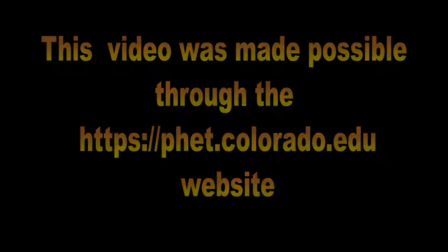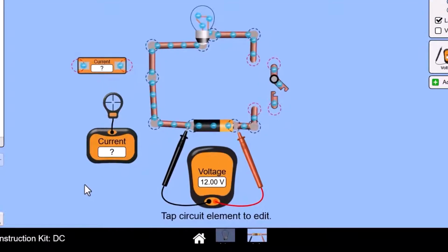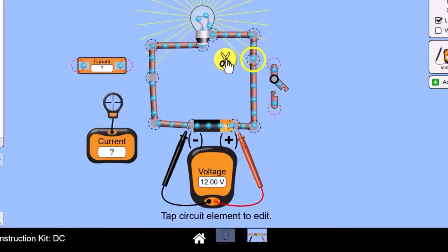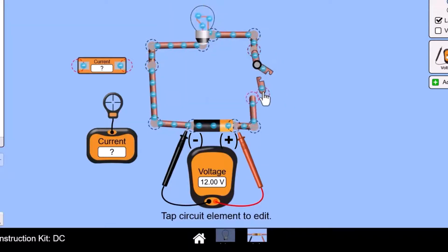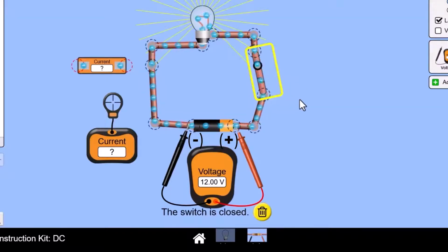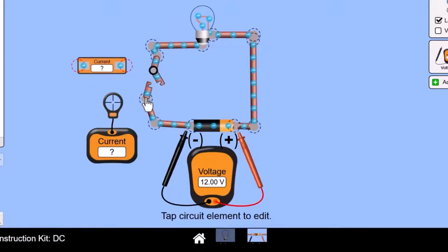Electrical shorts, opens, and amperage flow. An open electrical circuit is anything that prevents the electrons from flowing in the circuit. The break can be on the positive side or the negative side. The circuit is often controlled by installing a switch that opens and closes a circuit. The switch can be on the positive or the negative side of the circuit.